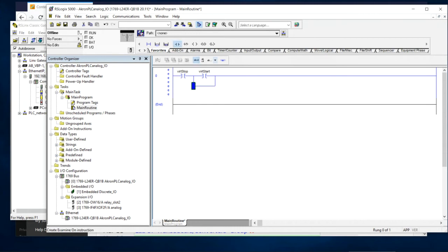Okay. And so notice here when you're dragging one of these around, the little green dots will show up where you're allowed to put it. Okay. And you just drag it around, and then you can click on this and change it to whatever you want here. And then since the virtual relay is an output, it automatically throws it over there to the outside.